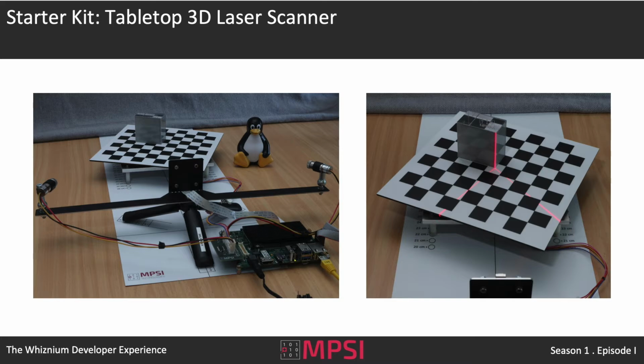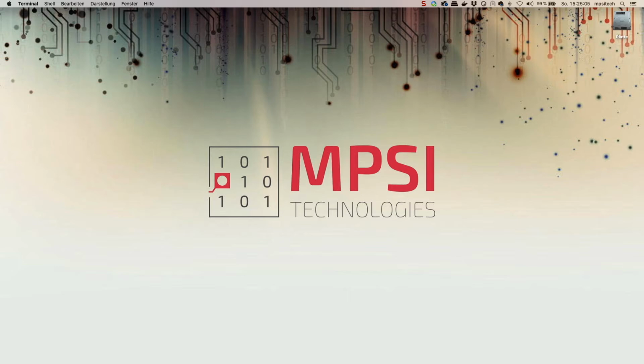And as here at MPSI we are big fans of programmable logic, we also have another version on offer, based on Digilent's Cora Z7, which uses Xilinx's low-cost Zynq 7010 device. Of course, we are always also monitoring very interesting developments in the industry, such as RISC-V, so be prepared for additional versions of the starter kit in future. But for this presentation, we will focus on the 2 mentioned boards.